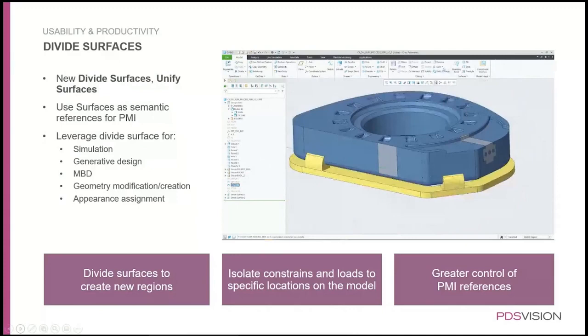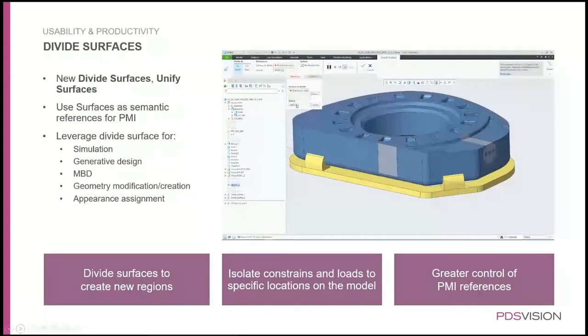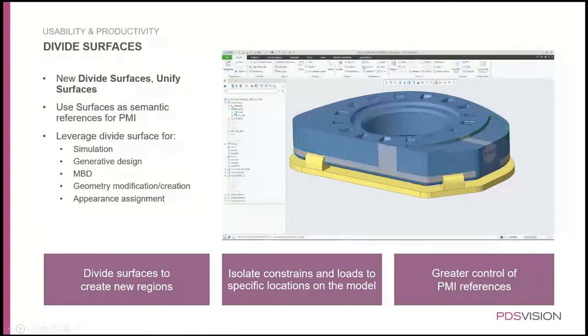Then a bit further with the demo, we divide a few more surfaces just to show you the functionality and that it exists. In here, we have just a horizontal line, and then you can have another selection of the bodies. You pick the top surface and use the shift key for the loop surfacing, and you are able to split the whole piece on the horizontal plane, which then enables you to decide which side you want to keep as a new surface, accept it, and have a new color in there.